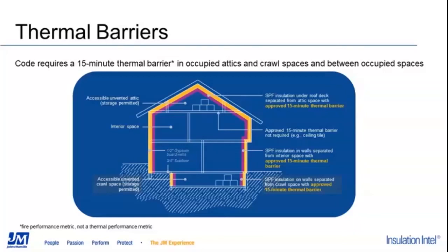All right. The next question we have, Mandy, we'll start with you: is there a difference between the acoustic properties of regular fiberglass batts versus sound batts versus mineral wool? Typically, no. Fiberglass batts, whether it's unfaced fiberglass or Sound Shield, are really the same product. The Sound Shield, like I mentioned, is just specifically marketed and packaged for sound control applications.